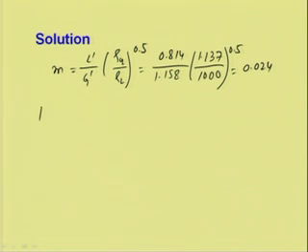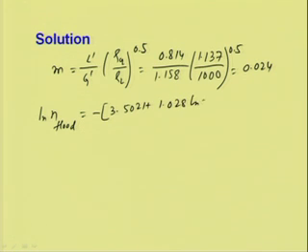Now, ln of F flat at flooding we can calculate as minus 3.5021 plus 1.028 ln M plus 0.11093 (ln M) square.